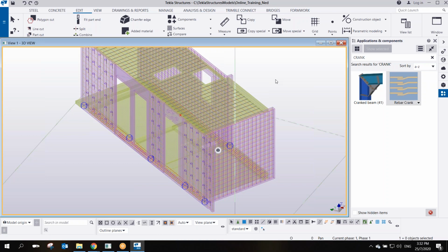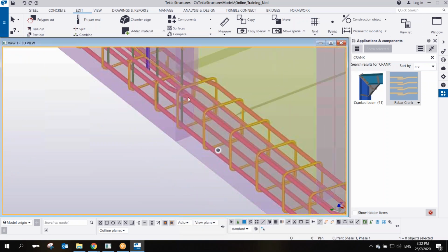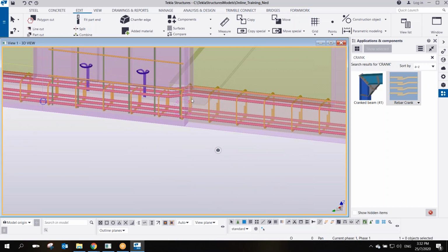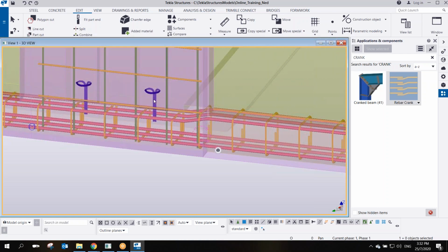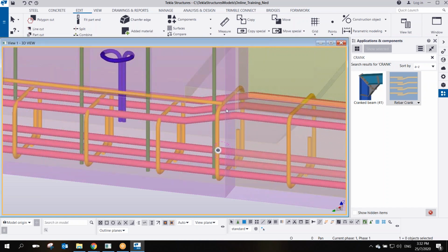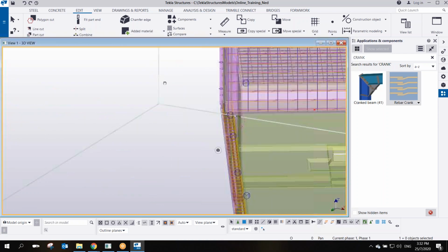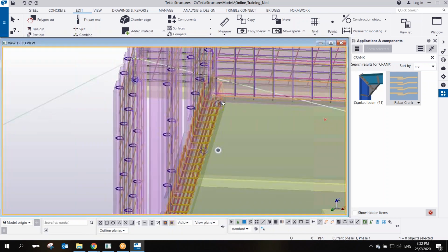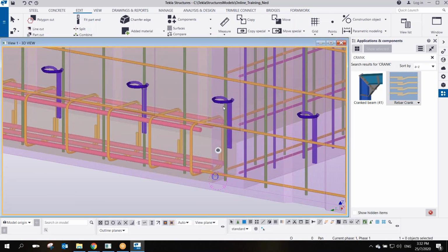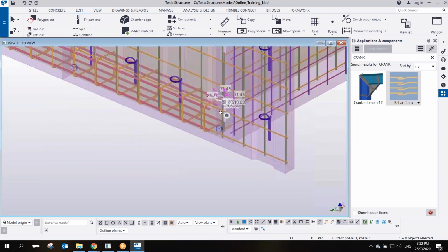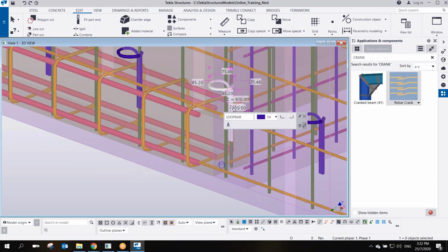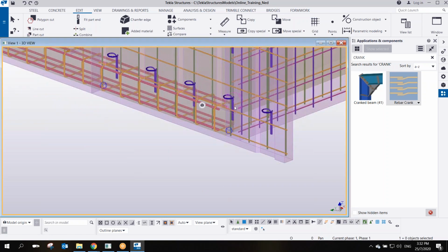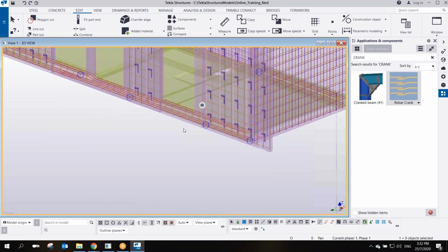As I've told you, we cannot put in all of the reinforcement here, but I'm putting some of the common reinforcement that we can add. The reinforcement here is a bit complicated, that's why I show it to you. So this cranking and then this. If you notice here again, my beam is integrated with the wall. That's why I added this reinforcement between the beam and the wall, and also this loop bar is quite not a straightforward way of creating. But once you create this one, then you can save that one, and then you can use that one later.